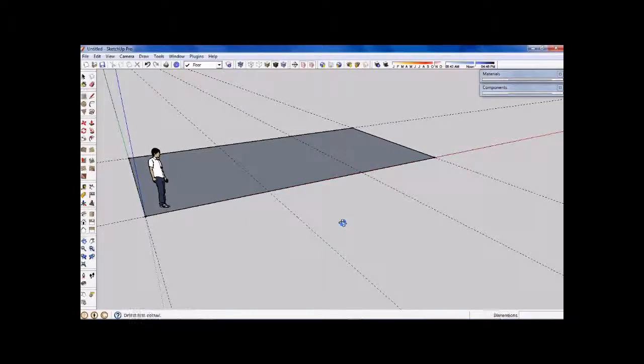Okay, so when you've got that top floor surface, we now need to give this floor a bit of thickness. Now I'm going to use that origin point level as being the height of the floor level in the building. Of course, we can't have the floor level in the building equal to the ground level outside. The floor needs to sit up at a level above the ground level. I would say at this stage we'll set something like 300 millimeters. So we need the slab, the top edge of the slab, to be 300 millimeters above ground level.